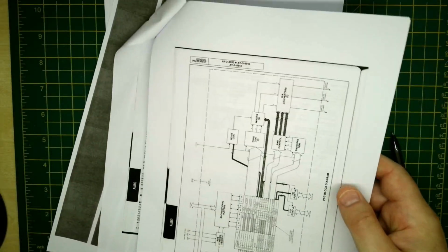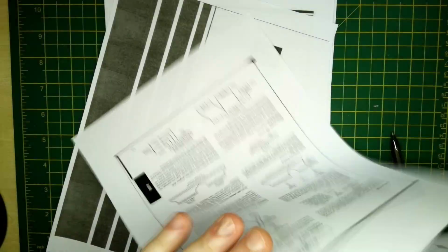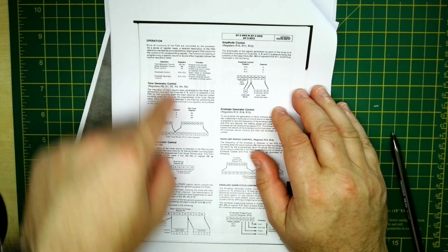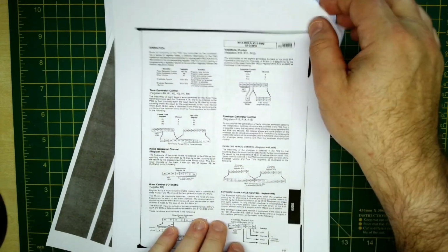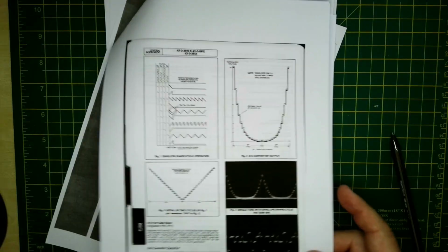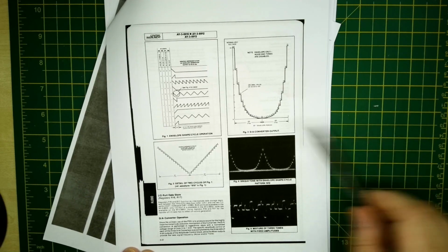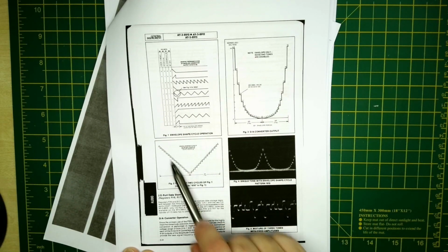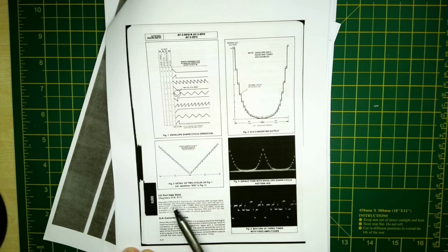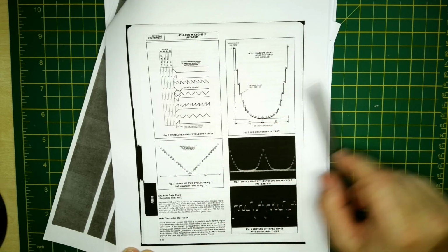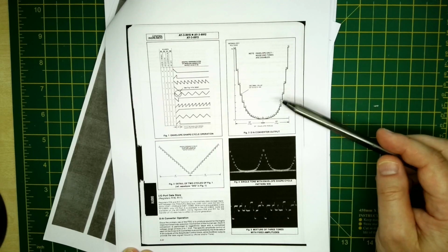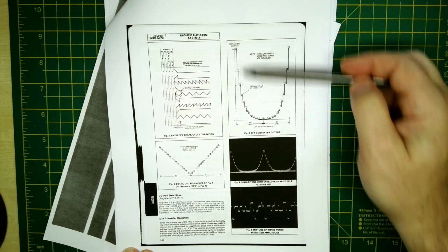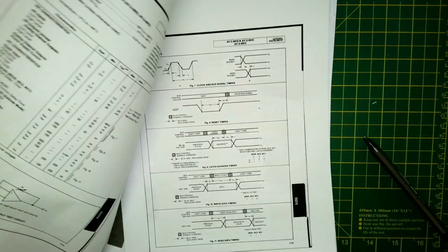The diagrams in the other document are a little bit bigger. You can see there's quite a bit of information about all the different registers, so there's much more detailed information about this in the other manual. This is showing the different envelope styles it's able to do, the different amplitude levels, and we've got a logarithmic D to A output. I think it has 16 levels, and you can see the variation in levels is logarithmic there.